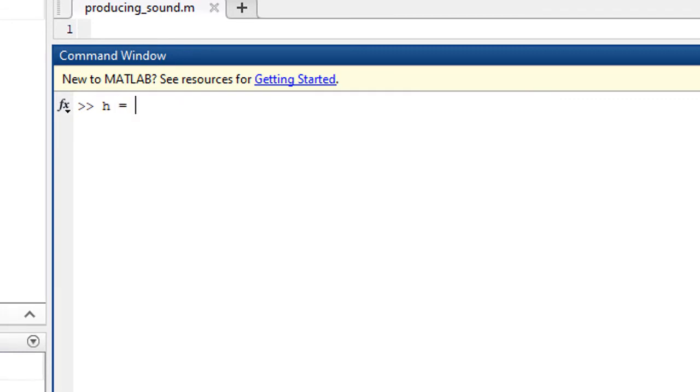The command to get the coefficients of an FIR filter is fir1. I have to pass totally 4 arguments here. First argument is order, but while giving it here I have to give order minus 1. Since it's a fifth order filter, I will be giving 4.